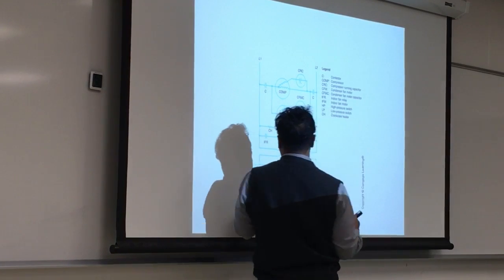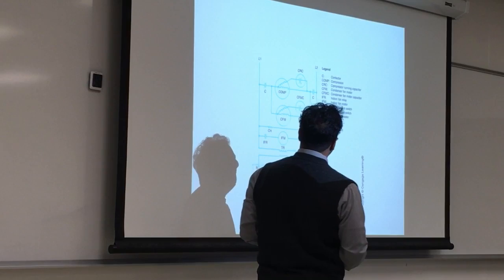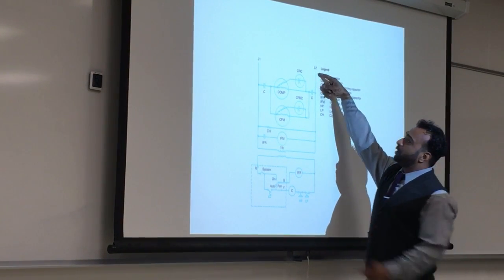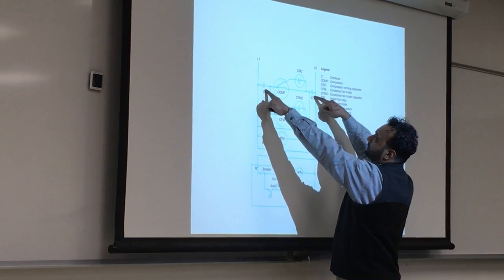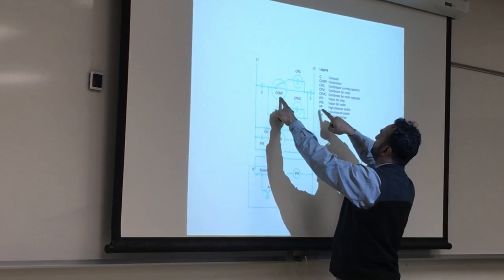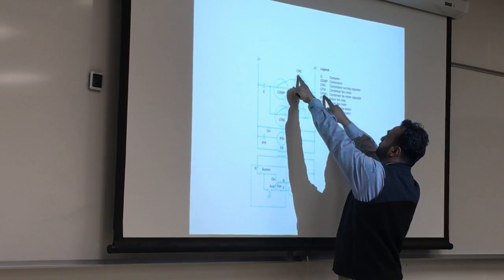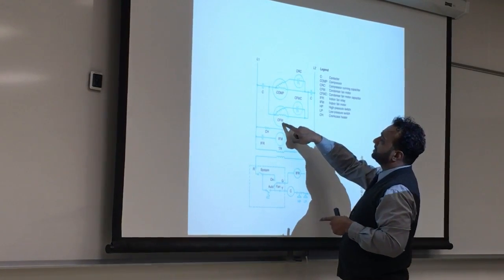Okay. And they also call this a ladder diagram. It looks like a ladder, and it goes top to bottom. We go down a little bit. What do we have here? Contactors. Excellent. What is this? It says over here, so we don't even have to guess. CRC, it's over here. Compressor running capacitor. Another capacitor here for the motors.